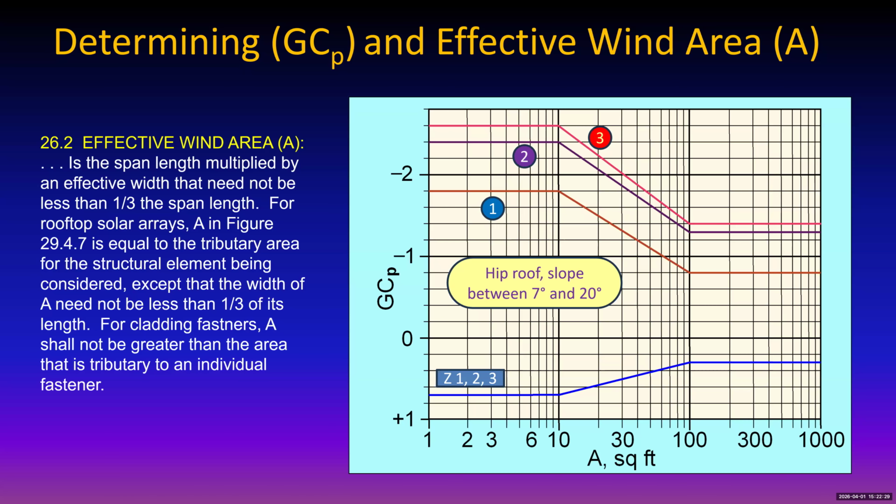See, qh is where you already took into account the square of the velocity of the wind, 115 squared, at the mean roof height, which is in this case around 15 feet, and the gamma E, gamma A. So we got 16.6 PSF. That's nowhere near that 75 PSF that we were looking at. So we can see that this is not half bad.